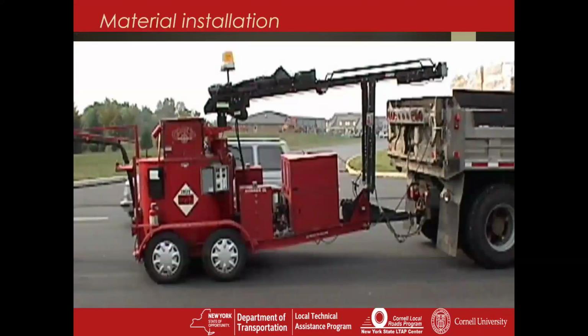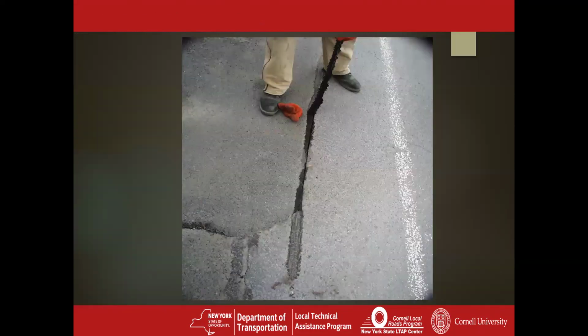I'm going to jump a slide. This is what happens if your crack isn't clean and dry. If your crack isn't clean and dry, that's freshly placed crack sealer material. That's a pretty expensive waste of time, because you put it in, it's not clean and dry, and it pulls right back out.